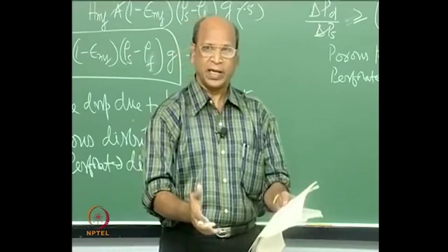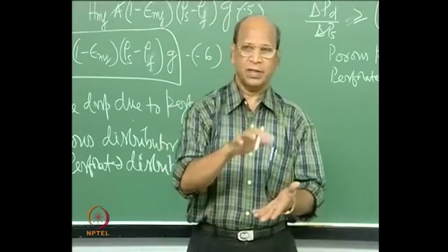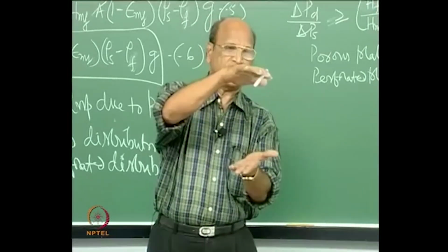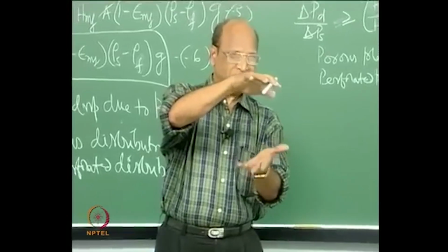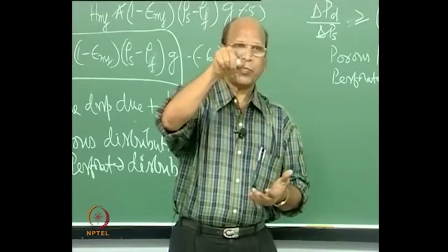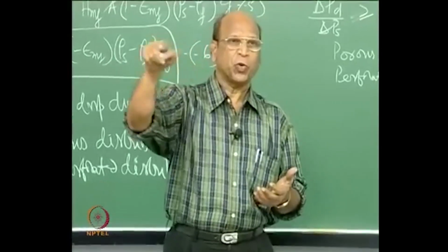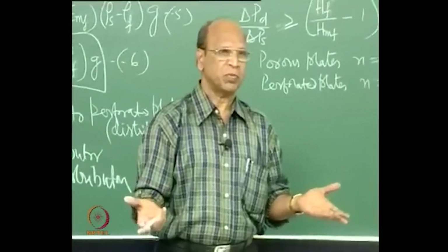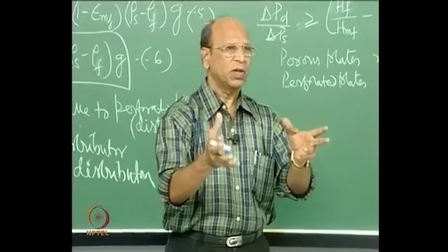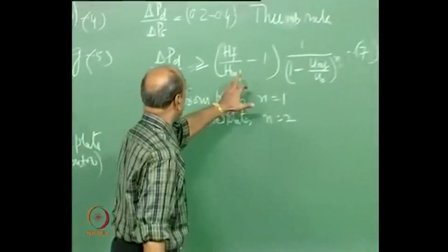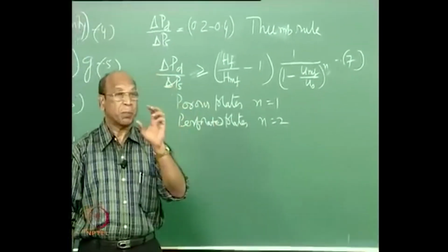It is the volume balance. It is the volume balance, right. So, when you have the packed bed, you have this height. When you have almost minimum fluidization velocity, Hf into 1 minus epsilon f equal to Hmf into 1 minus epsilon mf. That is simply volume balance, height changes. Okay. So, that is why one can find out if it is very good fluidization, particulate fluidization.